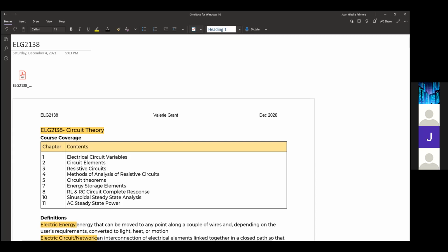Next up, we have elements, whether they're active or passive, depends on whether they create or absorb energy. You can think of it as the active ones creating the energy, they're the ones that are active, and the passive ones simply receiving it. Moving on, we have sources, which in general are what give you a constant voltage or a constant current. If they're independent, or a dependent source, which would give you one based on the voltage or current of another element, as we'll see in one of the examples.